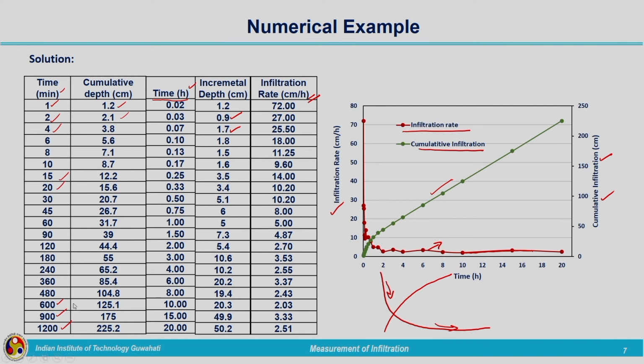Depending on that, as time elapses, you can increase the time duration with which the measurements are noted down. And regarding other types of infiltrometers, that is the tension infiltrometer, mini disc infiltrometer, and the flux-based approach, that is the rainfall simulator, some of the textbooks are dealing with those. As of this syllabus, I am not including that. Only conventional methods of measurement of infiltration are incorporated, such as the ring infiltrometers.